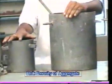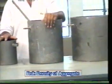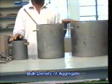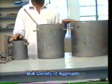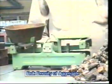Now let us see the apparatus required for the determination of bulk density of the aggregate. Cylindrical metal measures of 3 liter, 15 liter or 30 liter capacity, chosen depending upon the size of the aggregate to be tested. Tamping rod of 16 mm dia and 60 cm long, rounded at one end. A balance of 0.5% of weight of sample to be weighed.